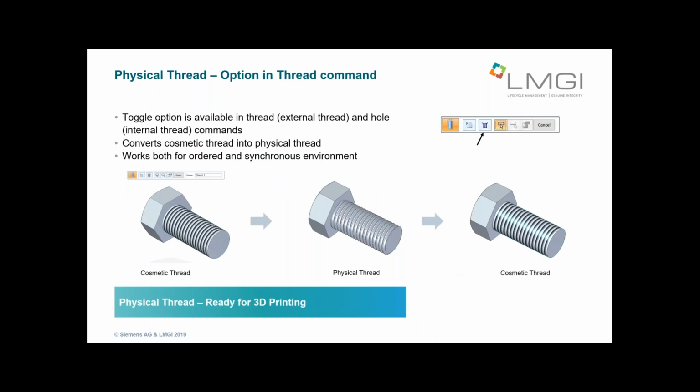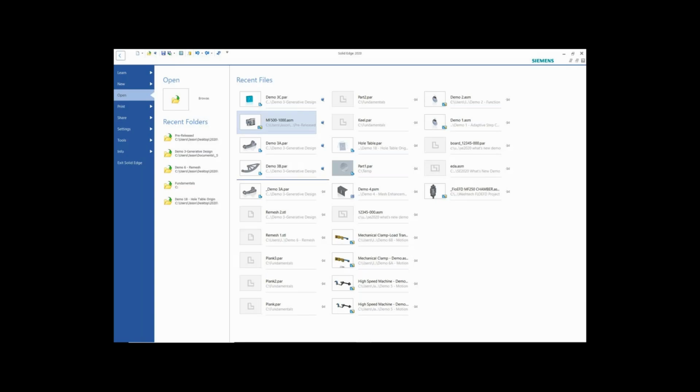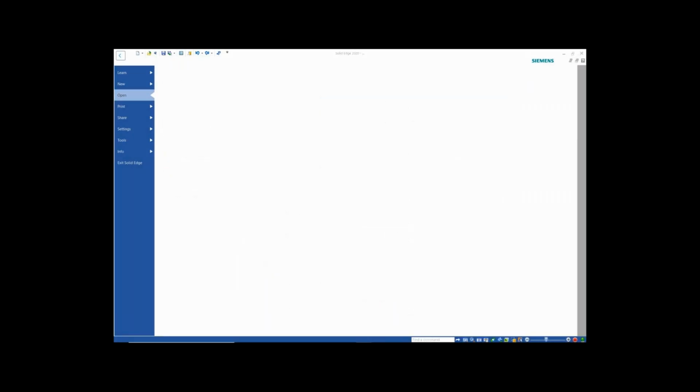Threaded holes are also handled; the software will model the physical thread for you. You'll see that in this coming demonstration. Depending on the process, it'll get you a really nice thread, or maybe a thread that's pretty close, and you might have to run a tap or a die over it, but at least for a larger thread, it may be good enough.